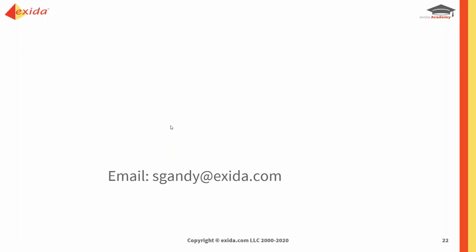Now, the proof test interval is normally a function of end user practices. So the end user may say, well, we're not going to entertain anything less than 2 years for proof test interval. And then you have to look at mission time. There's a whole other webinar I did on the relationship between the proof test interval, proof test coverage, and mission time, because there's no such thing as 100% proof test coverage. And if you think there is, then you're fooling yourself, because there isn't. You'll never get 100% on a valve, so don't even start with that.